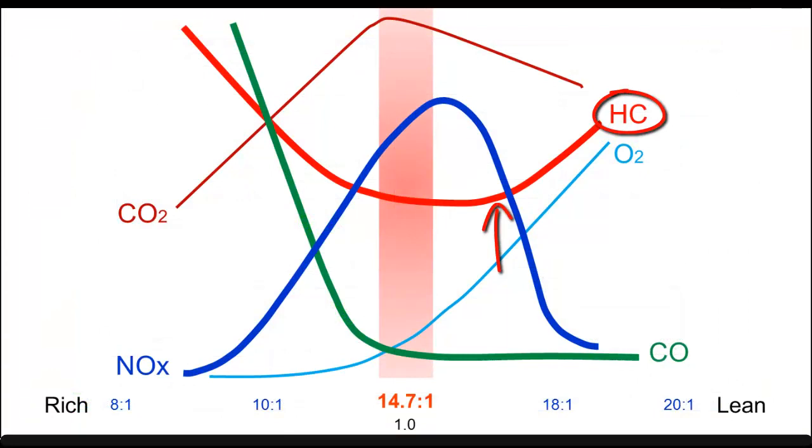Hydrocarbons slightly elevated at 154 parts per million. Carbon monoxide low at 0.085%. NOx low at 68 parts per million.